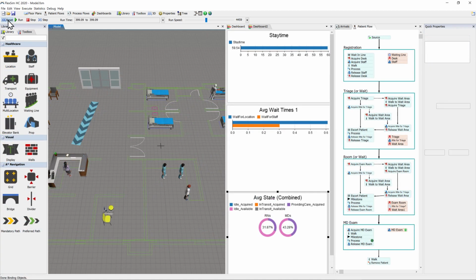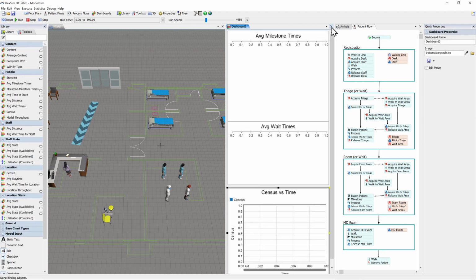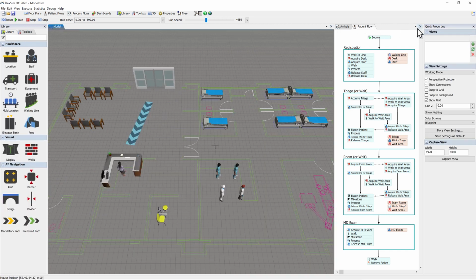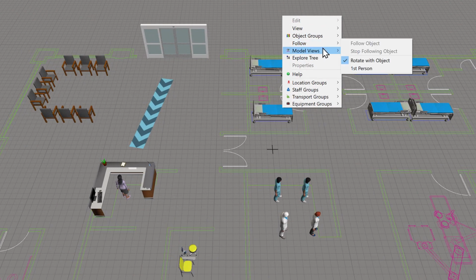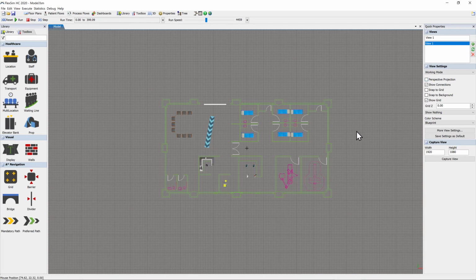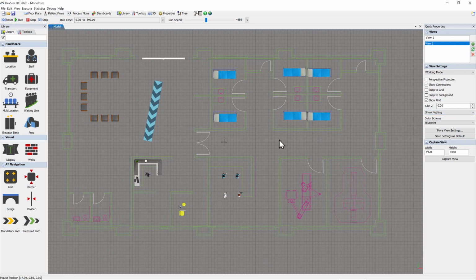Okay, let's stop, reset our model, and I want to close off a couple things here so that we can create some walking paths easy. Let me save this current view, and then I'll change to a top view and uncheck perspective. Okay, zoom in here and center it up, and ready to add what we call an A-star system. An A-star system is a bounded grid composed of barriers and dividers that travelers must negotiate as they try to find their shortest path to their destination.